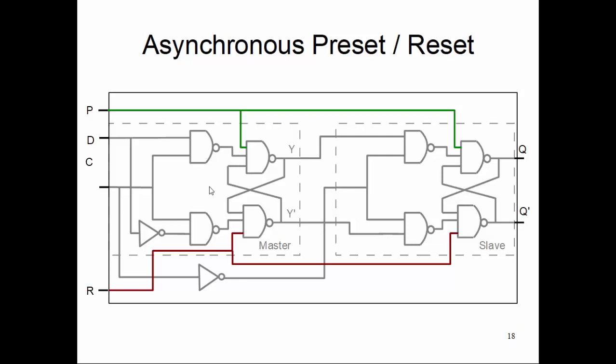Okay, and in every system, even when you power up a system, the system sends out preset reset signals. That is the first thing any digital system does: just go and make all my storage elements a known state. Okay, deterministic zero condition, as in my theoretical model of a sequential circuit. Okay, so that's my preset reset.